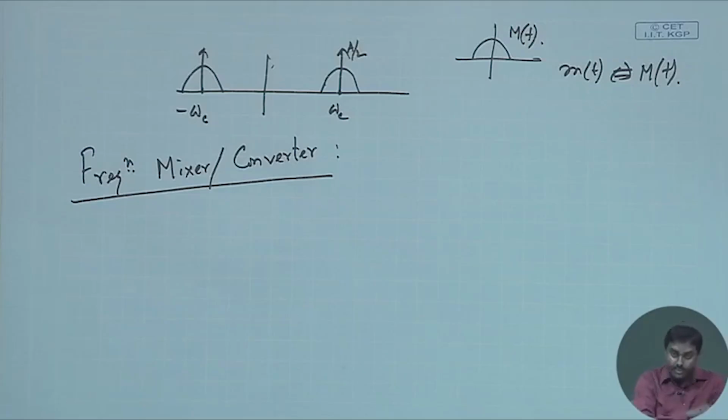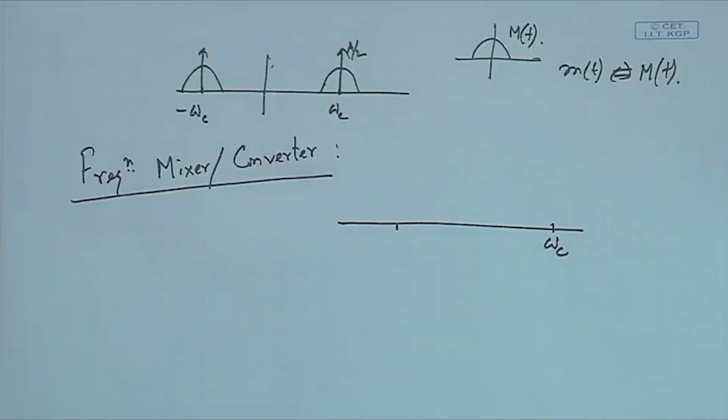So, generally what will be happening, suppose I wish to put some signal at a higher frequency. Okay. So, at that higher frequency, let us say the available frequency, because I need to get a frequency slot which is in the media nobody is occupying. Okay. So, that might be pretty high. So, what I need to do while putting, I need to modulate with that omega c, but in between I might have to do some signal processing, like I might have to amplify the signal and so on, some other signal processing I might have to employ.